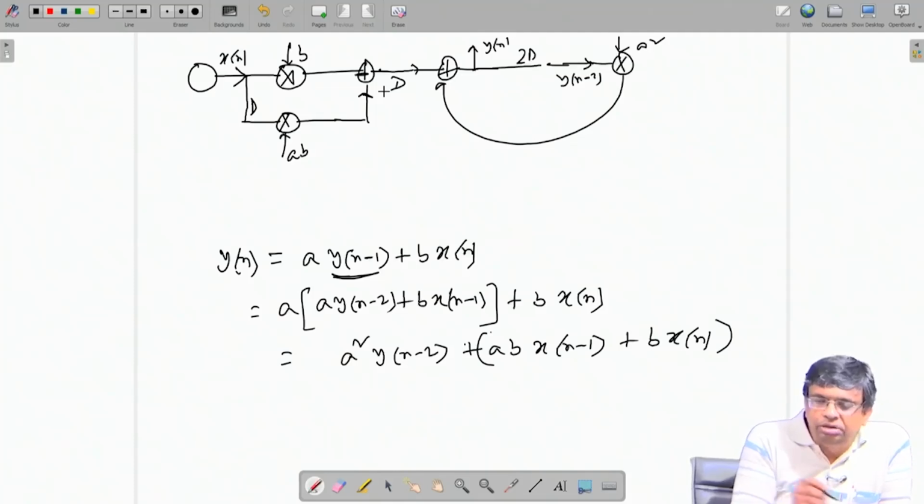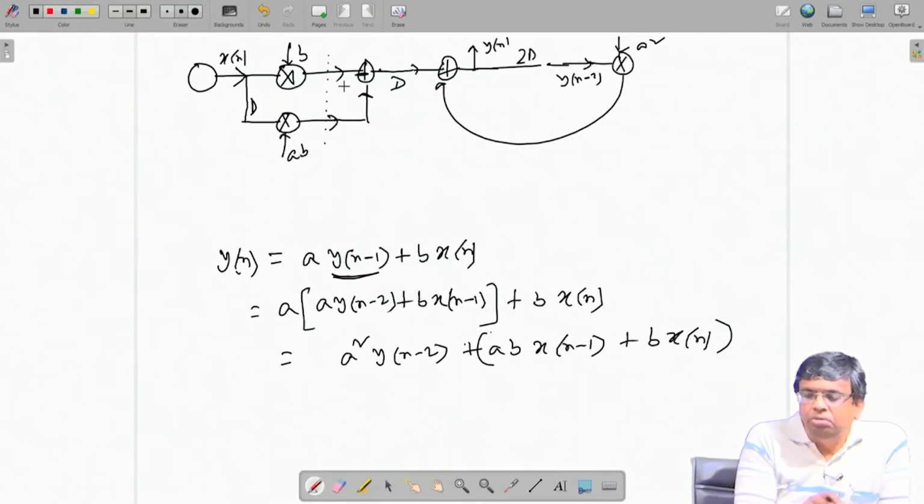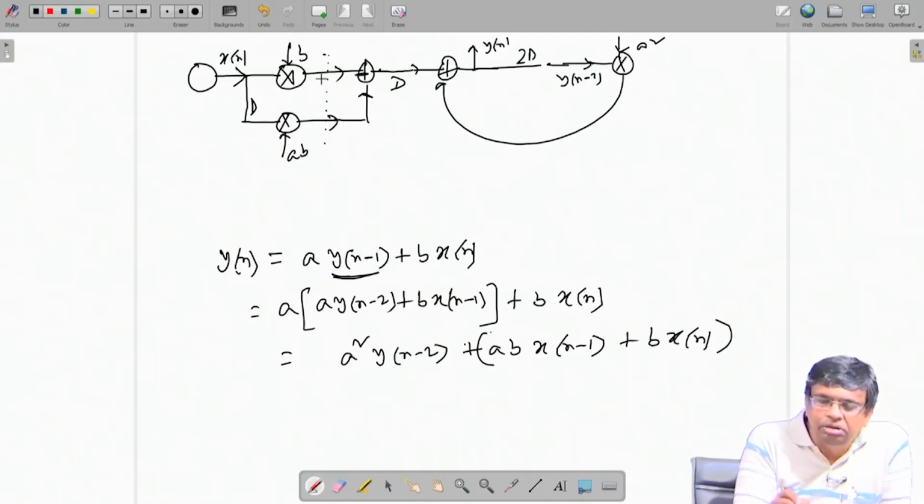So, on this side, and here also I can do a cut set retiming. Okay. So, I can bring there, this is also forward direction. So, this is one side, the left hand side is another side. I have only one direction, 2 edges. So, I can happily add any delay here. So, I bring D here, D here.